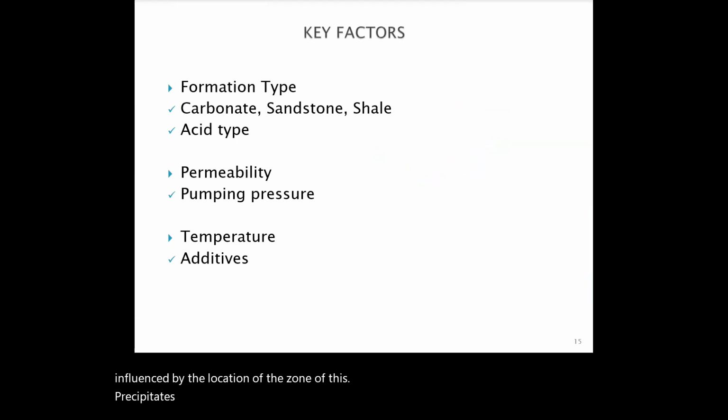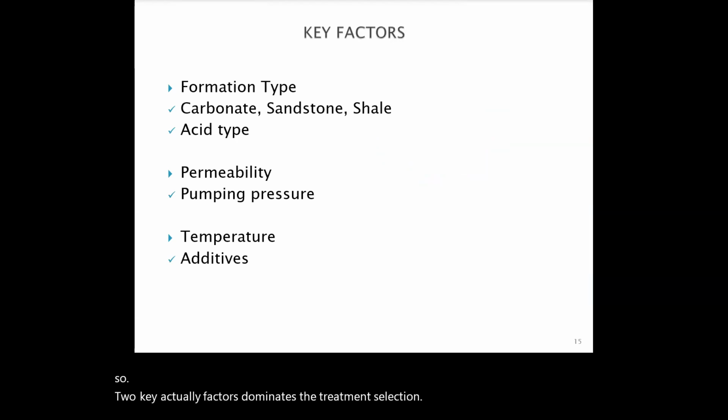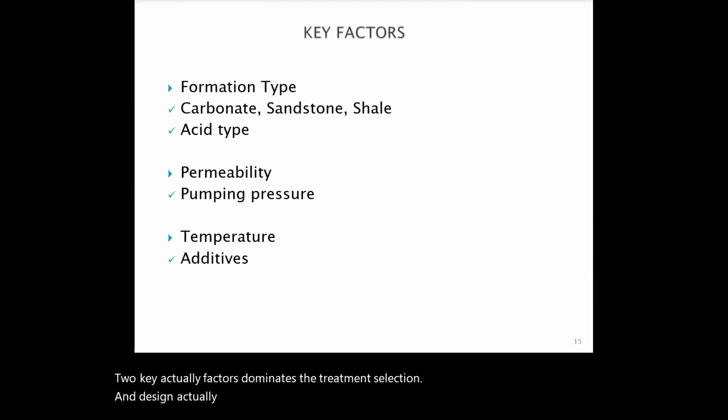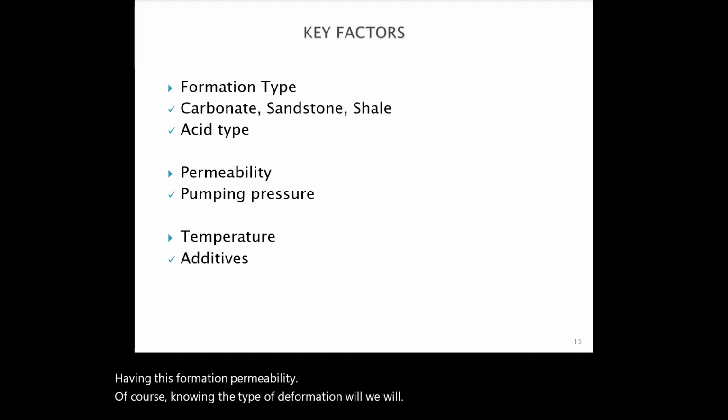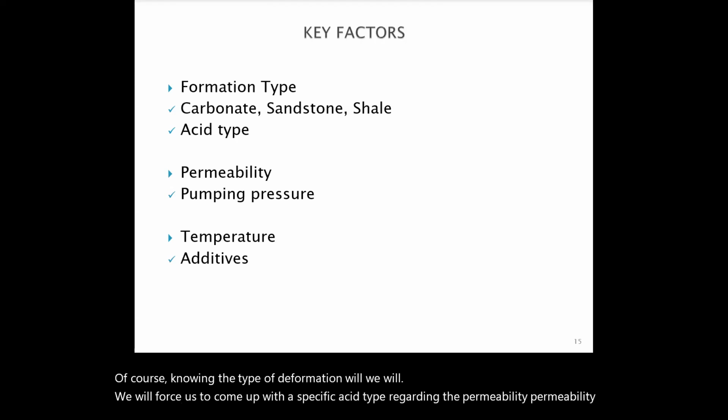Okay, so two key factors dominate the treatment selection and design. The first is the formation type, whether it's carbonate, sandstone, or shale, and the second is the formation permeability. Of course, knowing the type of the formation will force us to come up with a specific acid type. Regarding the permeability, it will help us come up with the pumping pressure.